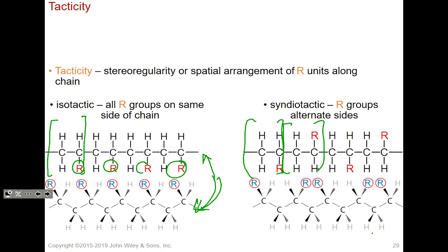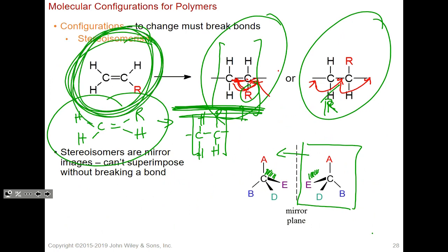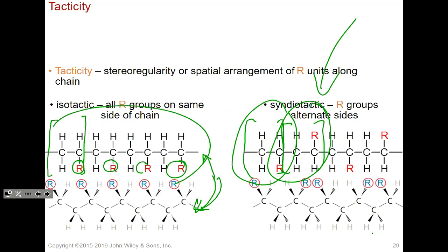And then you would end up with something that looks more like this, right? So do you recognize that this is one of the mers, and this is another mer? Just based on where the R is, from the monomer to the mer to then the polymerized states. But let's say your vendor absolutely guarantees you 100% this. Then you can polymerize it, and it would look something like this.